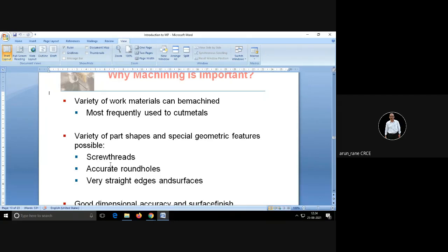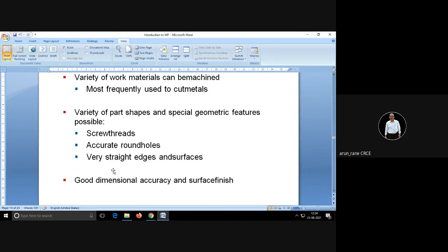If the cylinder hole size is more, then the piston will wobble inside that. The piston will not be guided properly. So there is very little clearance between cylinder and piston. So the holes are ground, they are honed. If you want that much accuracy, you will not get it in casting, forging, or powder metallurgy. You will always get a rough surface.